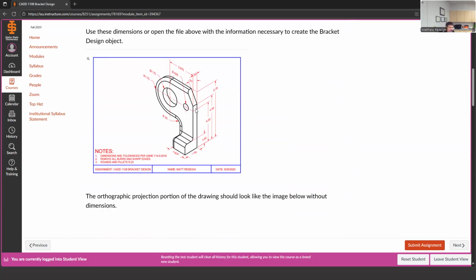And then yesterday I said maybe I would use this as my bottom and this is my front. And I do like that. It is a more stable part position. And if you've begun that drawing like that, that is so great. I'll totally accept it, because that's the way I talked myself through it yesterday. To lay this down as the bottom would be a stable part position. The front view would be this surface here, and it would have great detail in the front view.